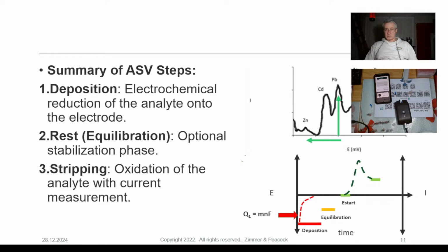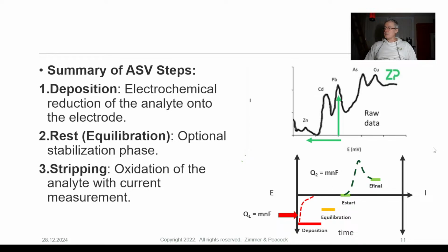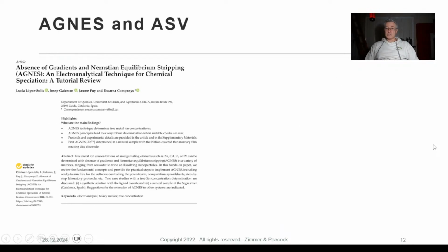The technique is a voltammetry technique, and it works pretty well. Basically the area under that curve is proportional to how much lead is actually in that sample. And we turn that in real time into a concentration and send that back to people's smartphones. But we're not excluding them from having the raw data.